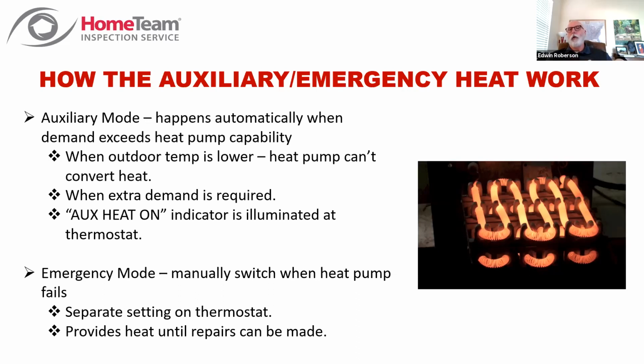And then the whole thing will cut off, but you'll be heating with heat strips once you get down to those lower temperatures, because the heat pump just can't do its job. You go into the northern part of the US and you won't see any heat pumps because there's not enough heat in the air. You go to extreme southern parts of the US and you won't see any gas furnaces because heat pumps can do everything you need the most efficient way. Here, we've got a mix of both.